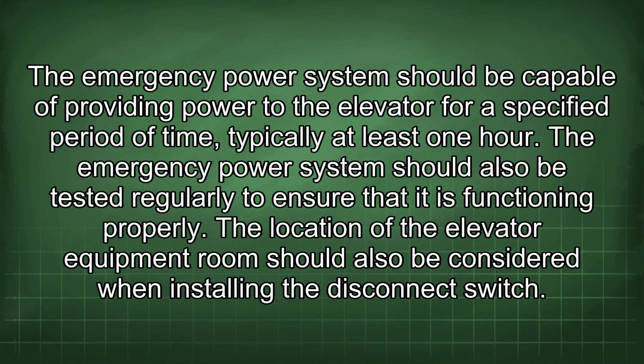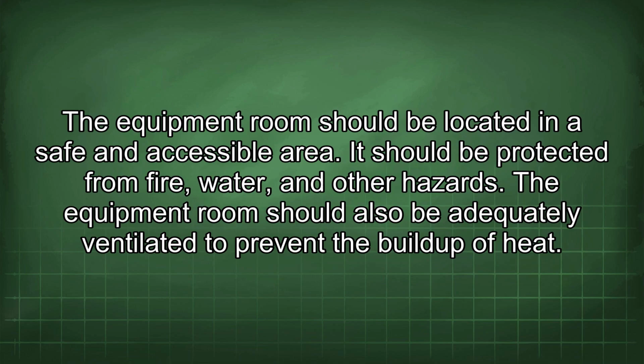The location of the elevator equipment room should also be considered when installing the disconnect switch. The equipment room should be located in a safe and accessible area. It should be protected from fire, water, and other hazards. The equipment room should also be adequately ventilated to prevent the buildup of heat.